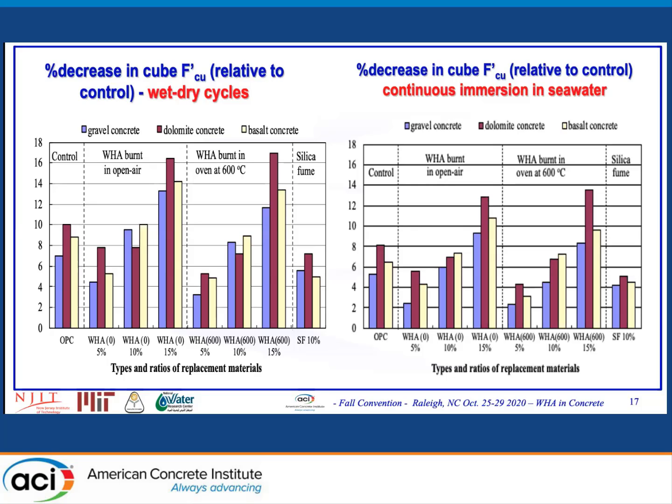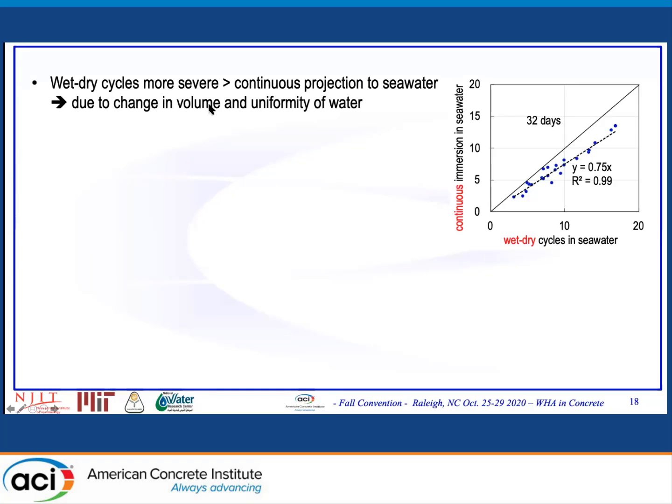As we can obviously see, the wet-dry cycles are more severe than continuous immersion, and this can be clearly shown by this relationship. So it means the wet-dry is more severe in deteriorating the compressive strength of the materials.